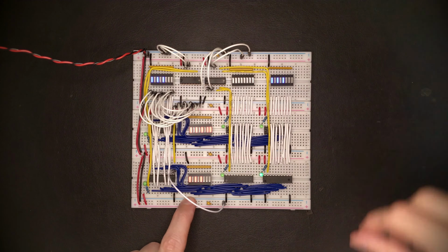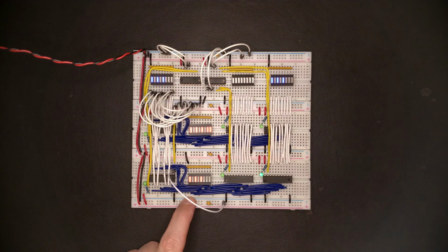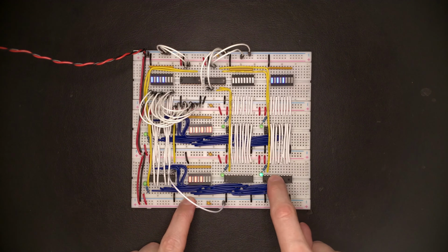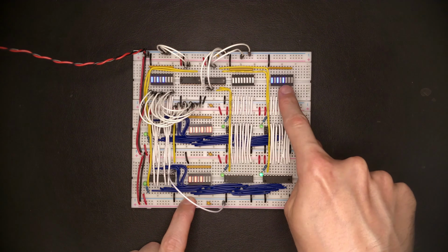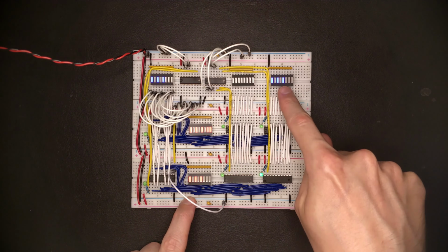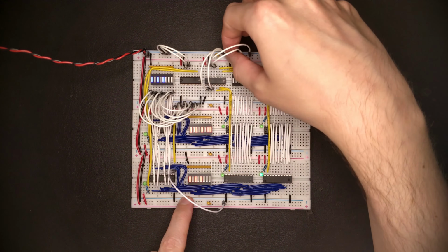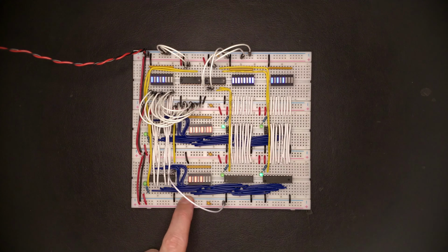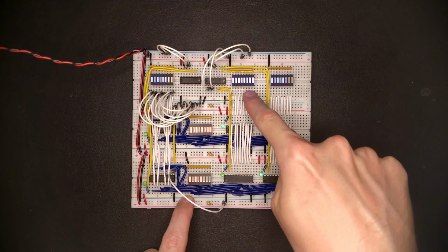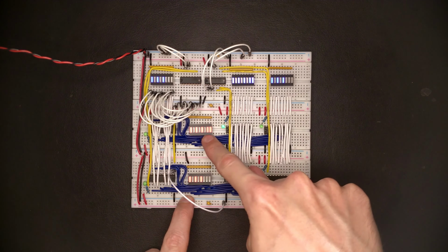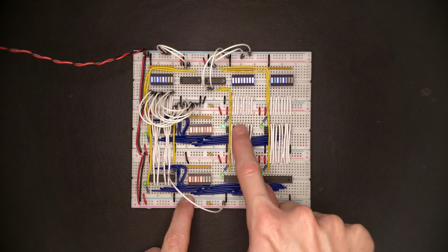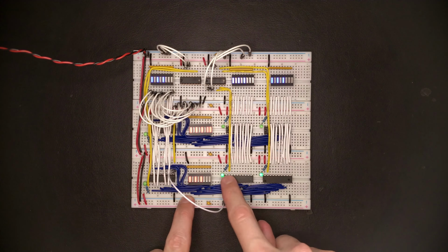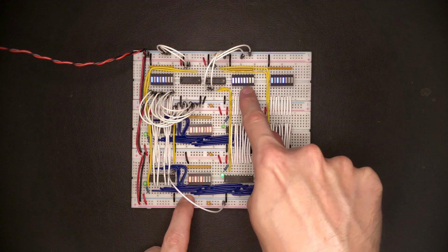And similarly, we can pick address 2, which is the second register. And as you can see, the output enable goes high for this driver buffer here and produces the value of register 2 up here at the read data port. And similarly for the address 1 here, we can pick, for example, 1 for the read address 1, which is going to produce the value of the first register on the first read data bus. Or we can change this to 2, which then effectively reads out the second register through this read port of the register file.